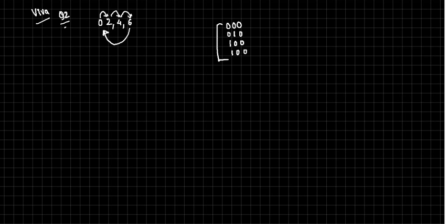And what is the usual procedure? We look at the highest state. What is that? 6. To represent 6 in binary, we require 3 bits. But that's not true. See the pattern in which this is appearing: 0, 0, 0, 0, 1, 0, 1, 0, 0, 1, 1, 0. One bit is always constant, so we can keep that, simply make it ground.